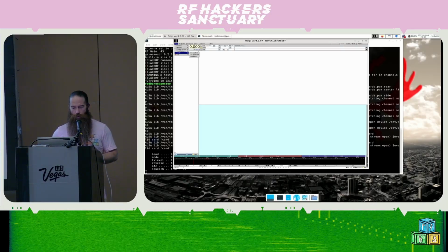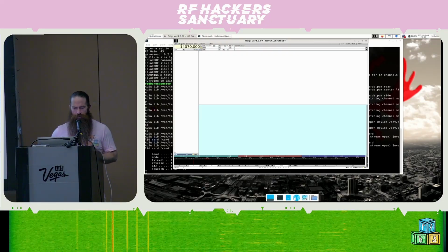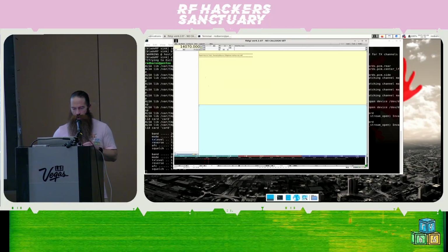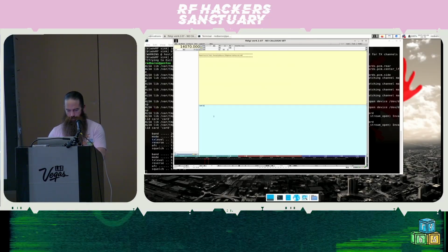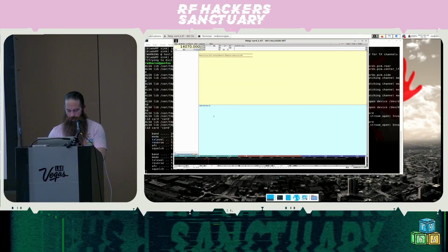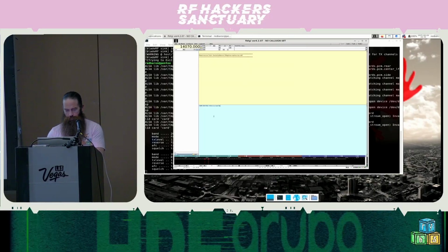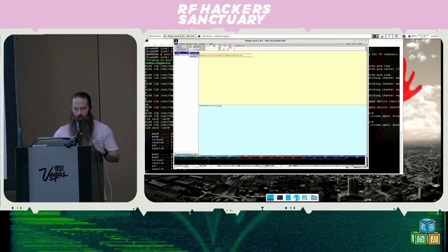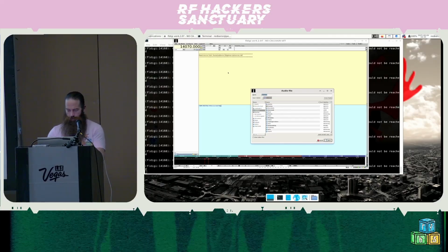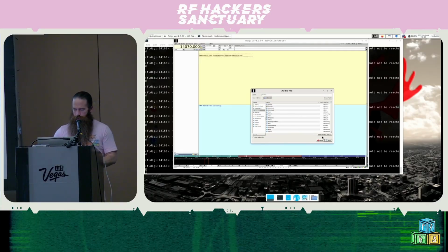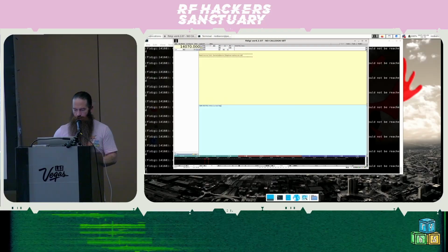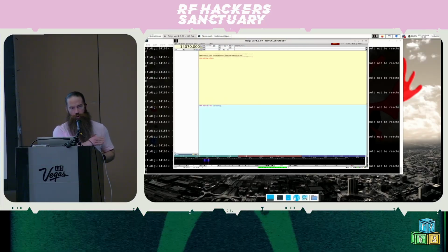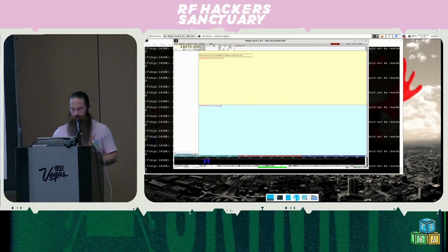these wave files. So let's say we wanted to generate a RTTY flag right now. If we picked RTTY 45 and then typed in "ham digital 9, this is a test flag," you could go up here in the audio menu, TX generate, generate a wave file, hit transmit, and it'll go through and actually put that into a wave file that you can then use in challengectl.